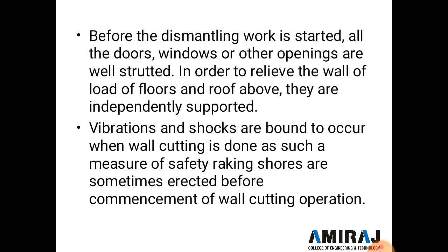And before the dismantling work is started, all the doors, windows and other openings are well strutted in order to relieve the wall of the load of the floor or roof above, so they are independently supported. And vibration and shock are bound to occur when the wall cutting is done. As such, as a measure of safety, raking shores are sometimes erected before commencement of the wall cutting operation.